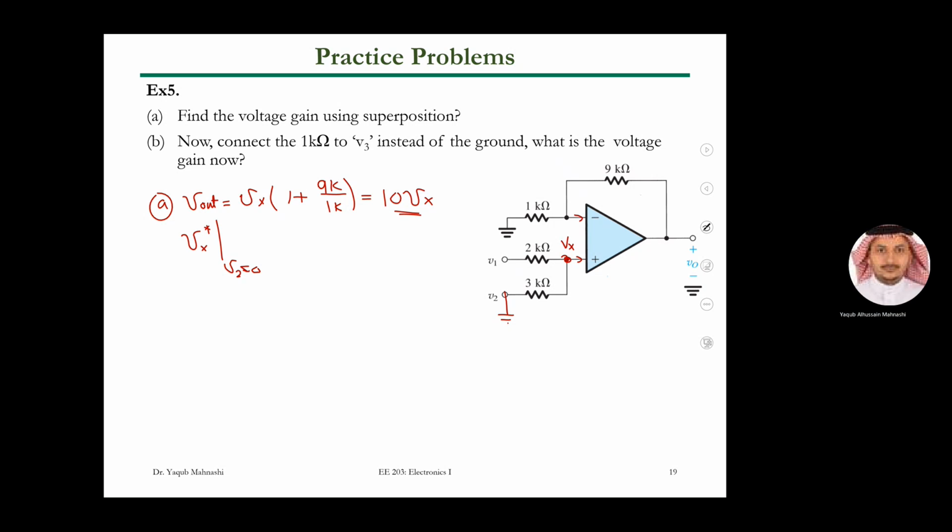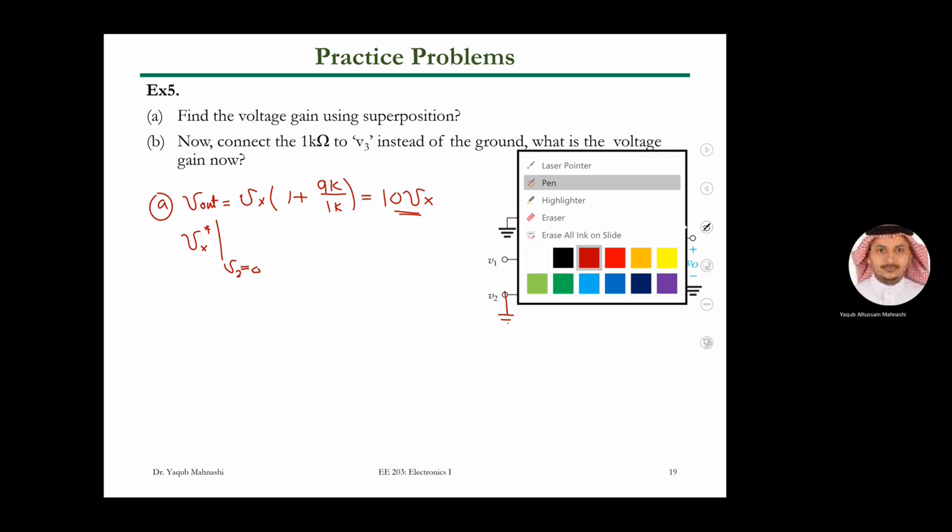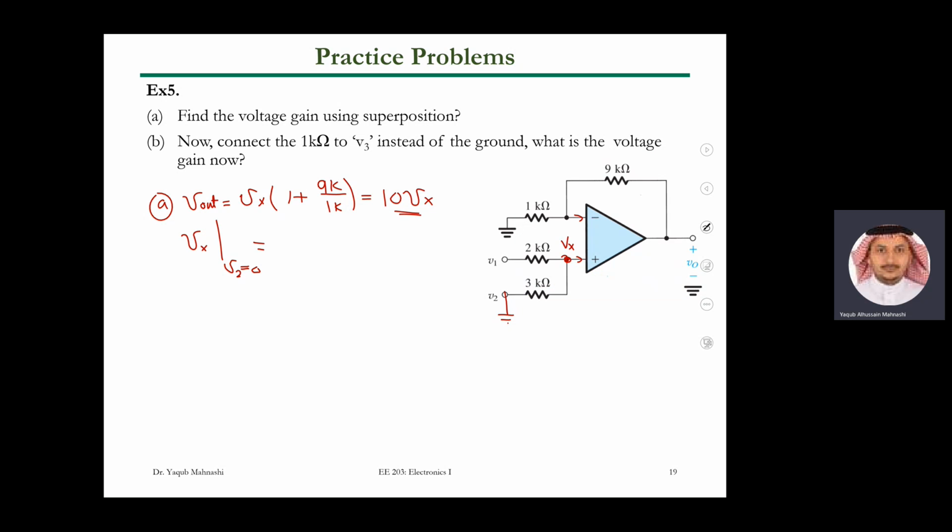So in this case, Vx star is due to V1, or saying that V2 is deactivated. Right? So if you have V2 deactivated, what is Vx, Shabab? And let me even take the star out. How much is this? I'm applying the voltage divider rule, VDR, because we know the current entering the OPAMP is 0. So as if you have only 2 resistors and 1 voltage source. So how much is Vx now? It will be the voltage source, which is V1, multiplied by 3 over 5.